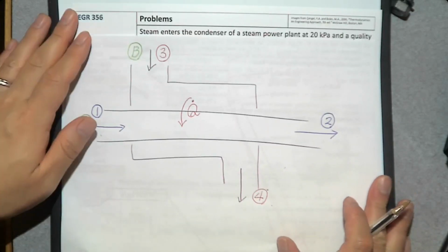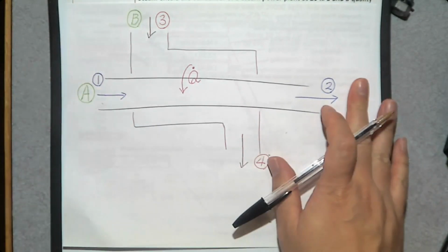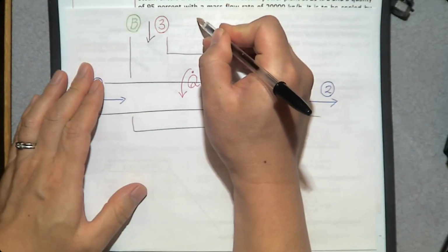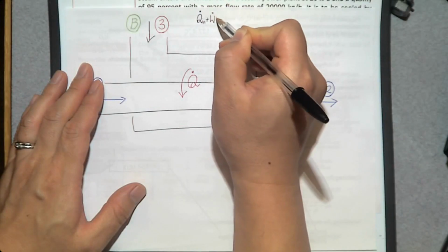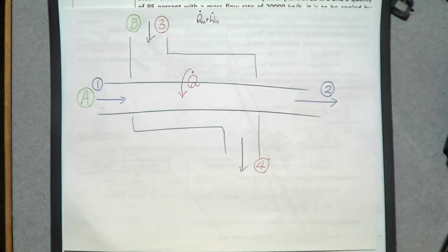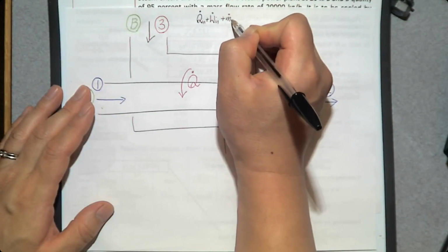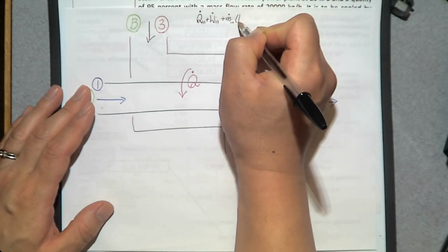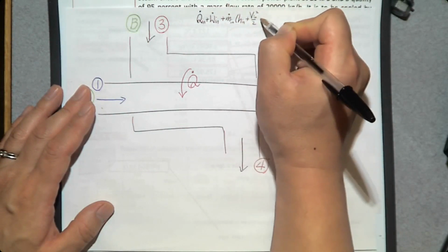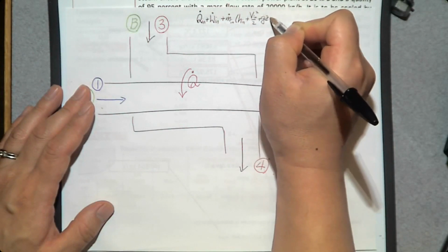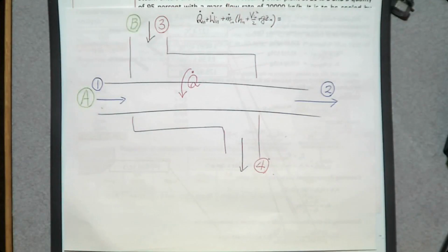So the general energy balance equation looks like this. Let me write the general energy balance equation first. Q dot in plus W dot in, and we have the one inlet. Let's assume that we have one inlet. Then M dot, at its inlet, it has enthalpy, kinetic energy, and potential energy, gravity times elevation Z. So these are energy transfer into a system.